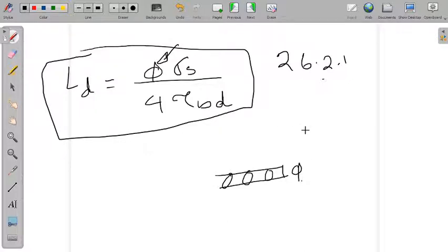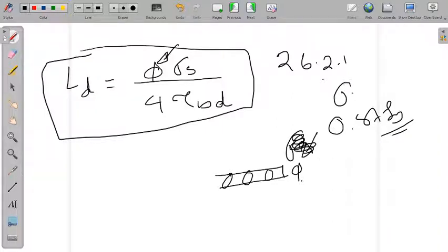Basically, for the limit state method of design, if you are using Fe 415 steel, then what is the stress? We can say 0.87 fy. So whether it is Fe415 or Fe250 or Fe500, whatever steel we are using, for the limit state method the stress is 0.87 fy. So sigma s is equal to 0.87 fy.